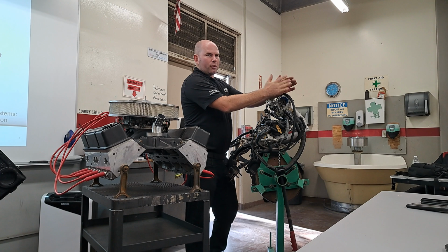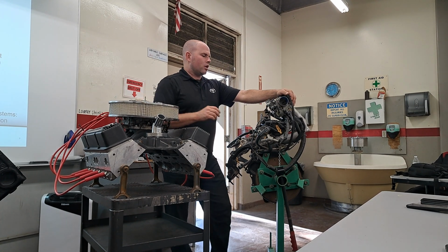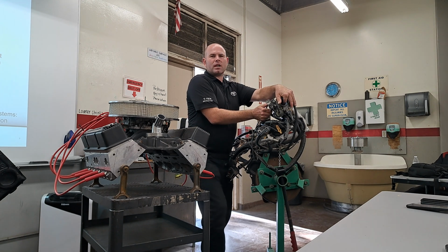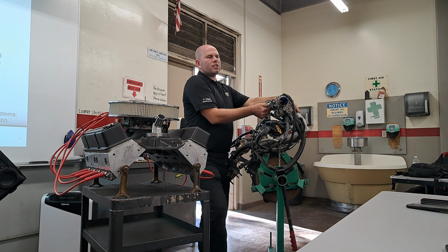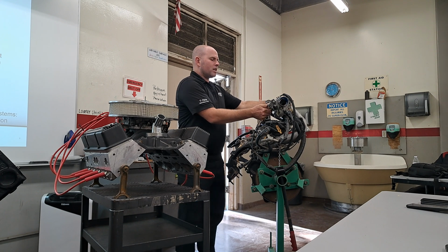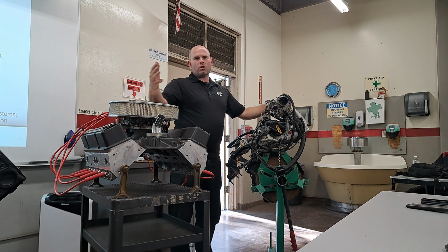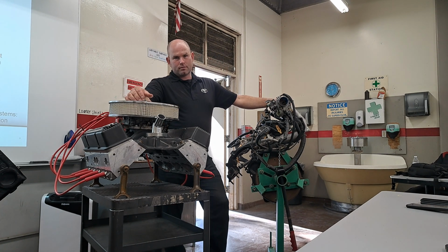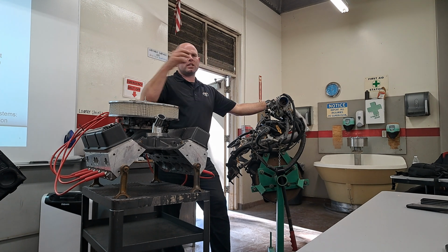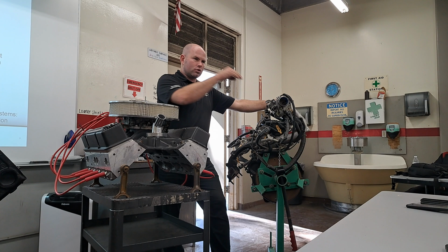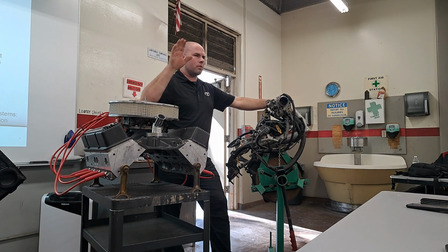This assembly is the throttle body. The throttle body's still there, but it's changed a bit. The throttle body was literally a valve. Sometimes we'll call that valve the butterfly. You ever heard it called the butterfly? It looks like the flapping wing of a butterfly. That was controlled by cable, and then of course you know we don't control it like that anymore, right? Instead, we put a motor right there, and that motor gets a signal from the ECM, and the ECM controls it. The ECM looks at a bunch of different inputs, mainly your pedal.